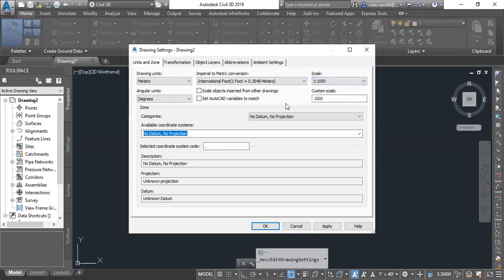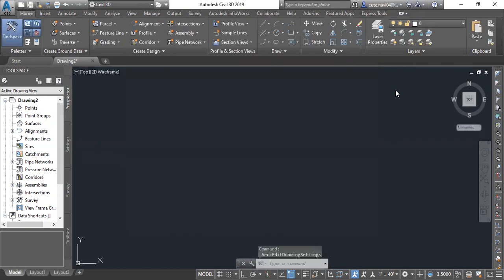So you can change them with your drawing, because at the downside you can see here you also have this scale and you can change it. Here we have a clue. When you open your imperial AutoCAD, you will see the scale in feet, 1 inch into 20 feet. So the scale is in feet, but we need metric if we are using meters.